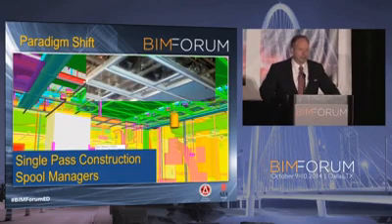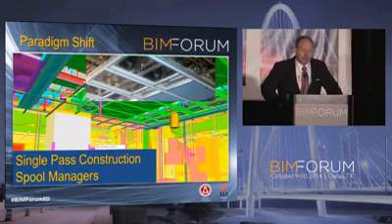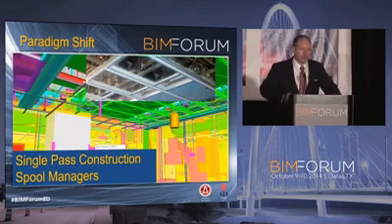They do their arm overs, they run them long, they come back, drywall goes in, they're waiting for the lights to figure out exactly where they're going to go. We have to move some studs and some track because they're not in the right spot. Everything doesn't line up. Single pass construction with X, Y, and Z coordinates with nothing measured off the floor, they can come in very first, run high, arm over, and put their heads in all in one shot.